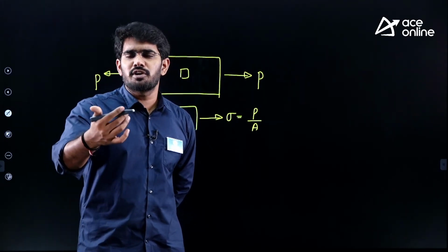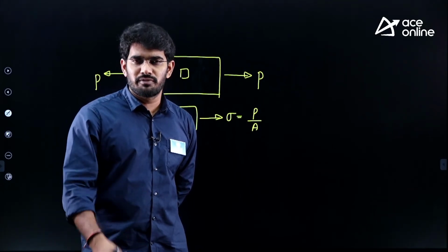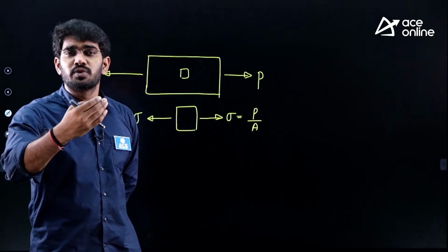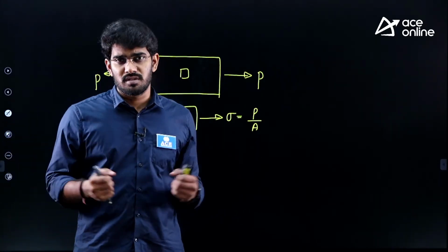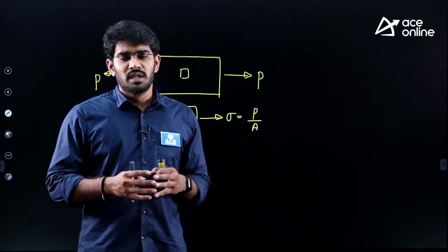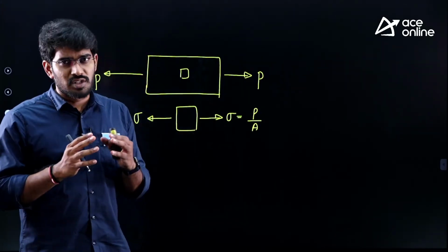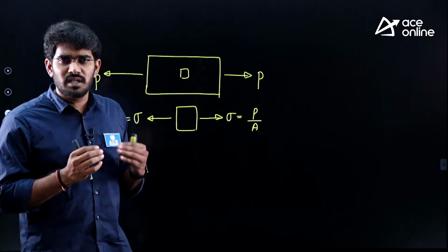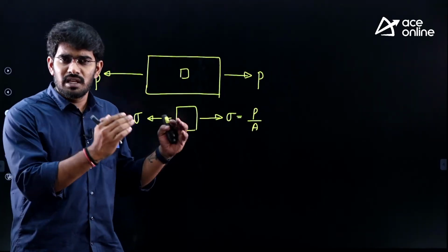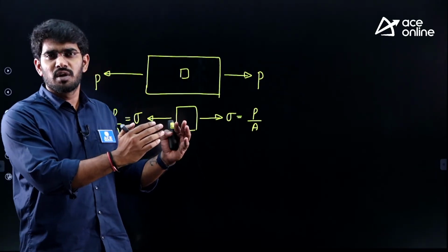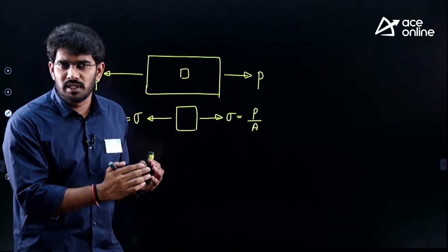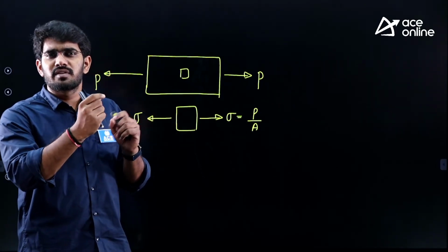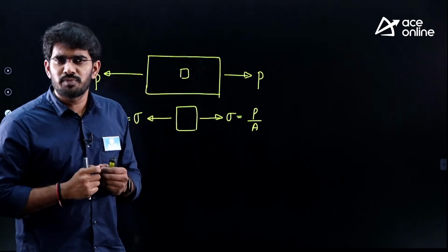Plastic deformation is considered to be permanent deformation. When the component is loaded into this region, it is getting damaged. Permanent damage is happening. If it is only within the elastic region, there is no permanent damage, and our component should not get damaged. This is our interest. So either a ductile or a brittle component has to be loaded only within the elastic region. The dividing point between elastic region and plastic region is considered to be the failure point.